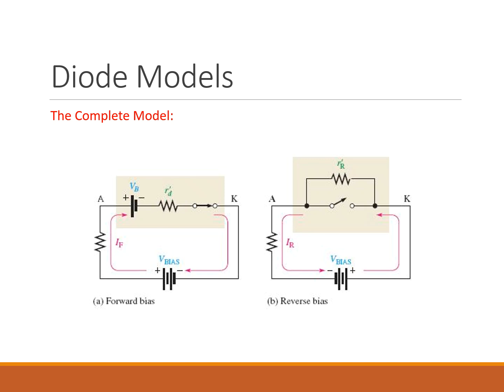The series resistor R sub D prime, which represents the diode's dynamic forward resistance. And then the closed switch to indicate that current is allowed to flow. And so what happens physically? Once your external voltage bias is greater than V sub B, current flows.